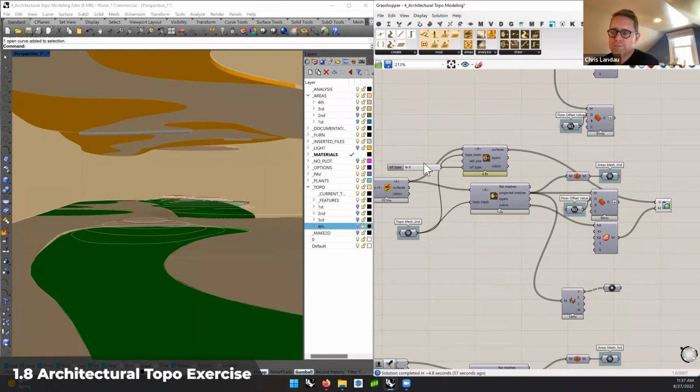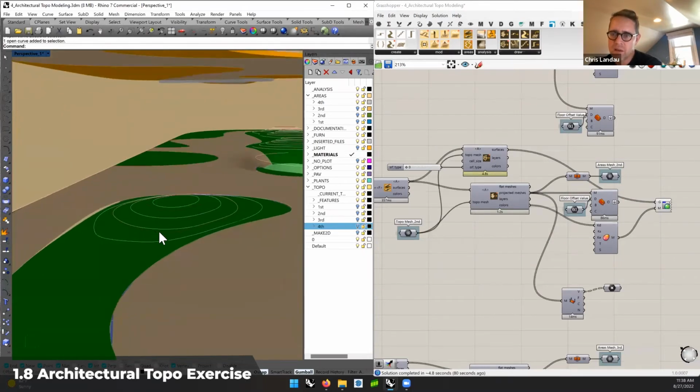And if you're not describing the topography accurately with break lines and whatever, then you're not going to get a very smooth mesh. And I think a lot of times people use the surface to make things look smooth where they haven't really figured things out, right? You can use a surface as an input for the geo set as well, to make things a little bit smoother ultimately.